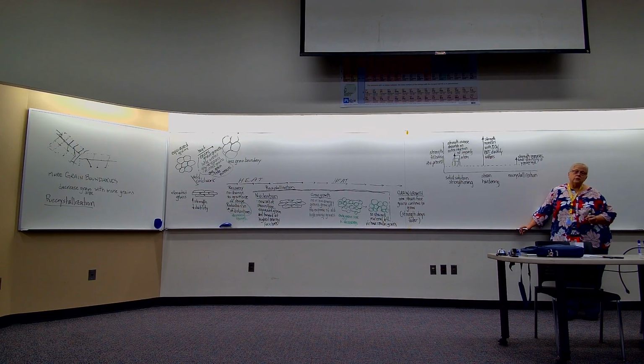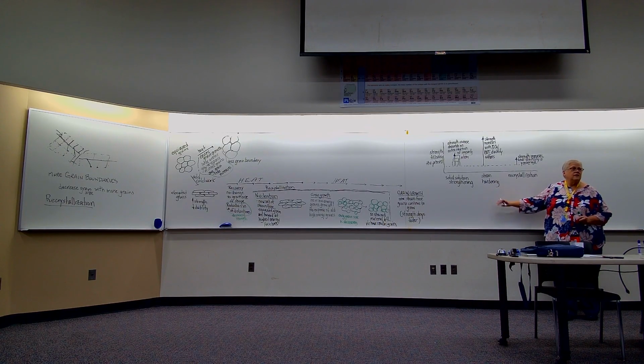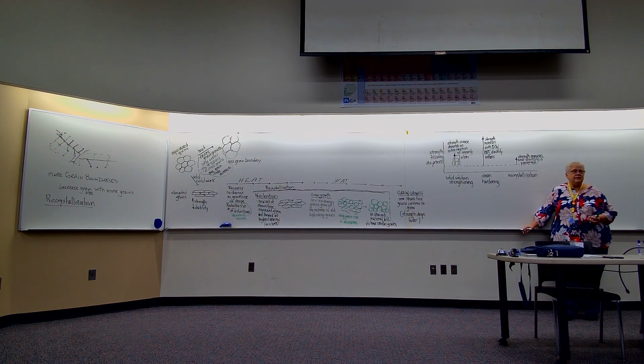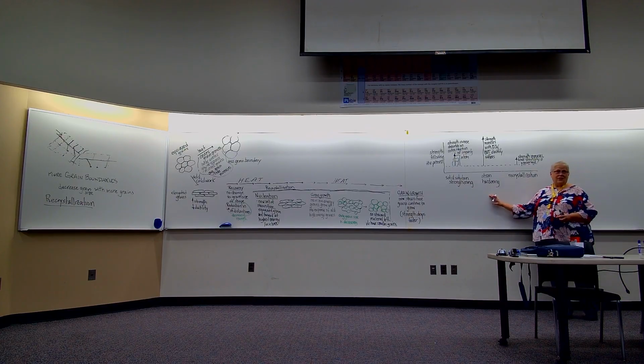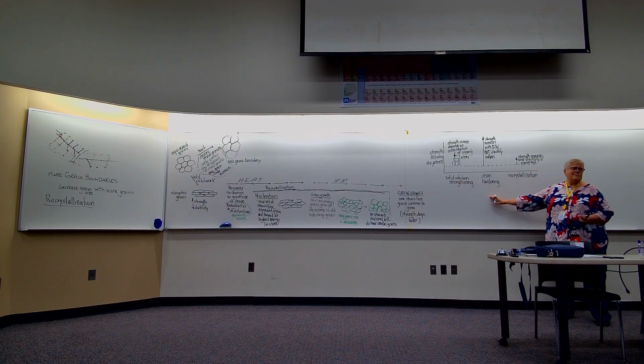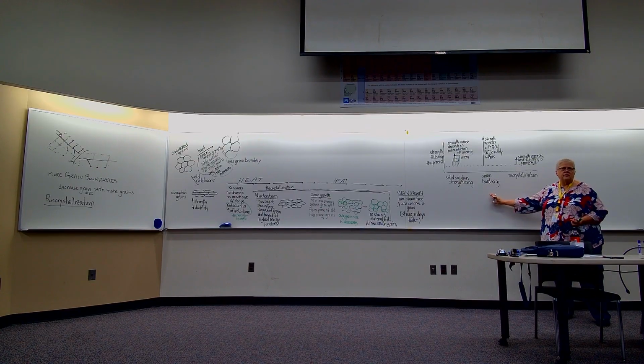I just need to make sure this component that I'm using cold work to strengthen isn't going to be in bending, isn't going to be in torsion, isn't going to be seeing impact, because brittleness will be a problem there. But it could be pretty easy. I mean, rolling a piece of steel isn't that difficult. It could be relatively easy to do this method.